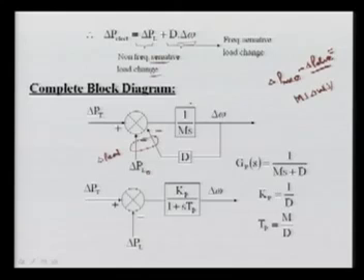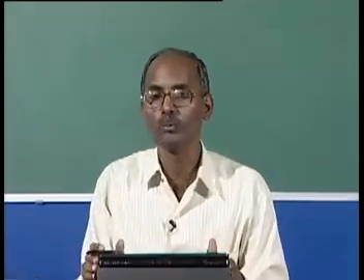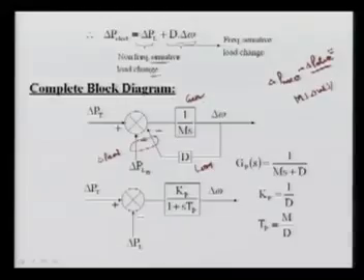So this is your generator model, this is your load model, and now we can combine this with the remaining modeling, that is governor and turbine, and then we'll see what loop we are getting. Now again we can simplify this loop because we have one closed loop here. So that can be simplified, here is nothing but we can get this GP, we call GPS, that is a transfer function of the power system, generator power system, means that includes your generator as well as the power system, so it is called GP.